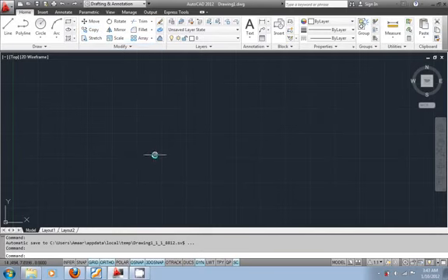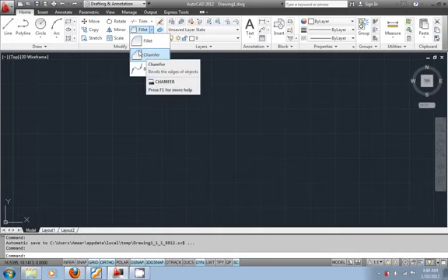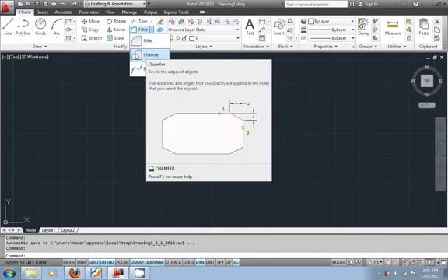Now this could be four chairs around a table, or this could be rows of cars arranged in a parking lot. It could be anything. You can always stretch it. You can always apply fillet. By fillet I mean the rounded edges at the corners. And you can always apply the chamfer command. The chamfer command is, as you can see, not rounded, but straightened edges of any object.